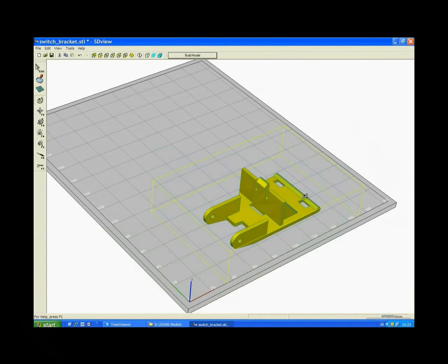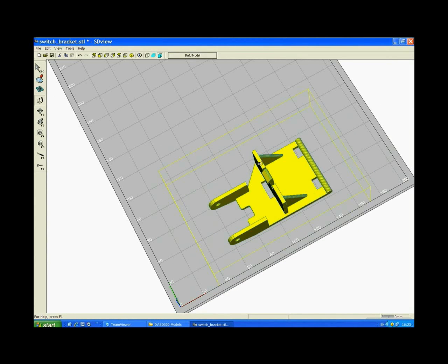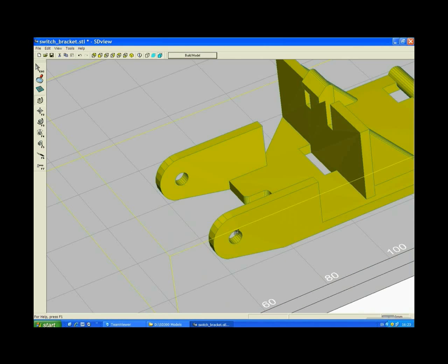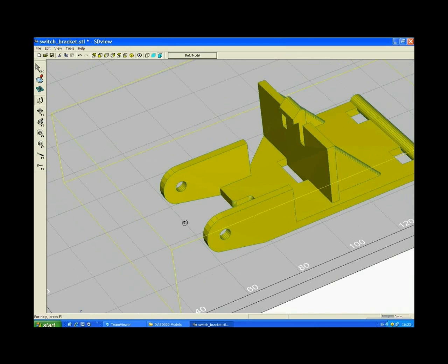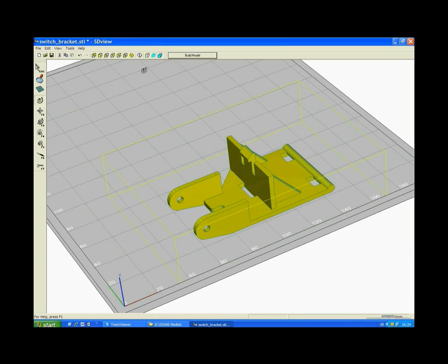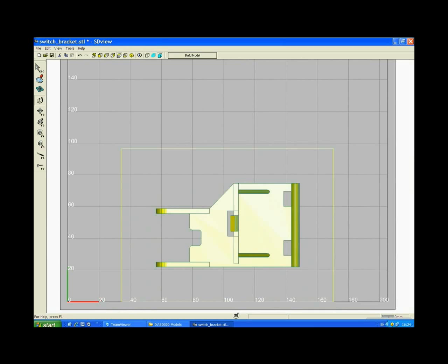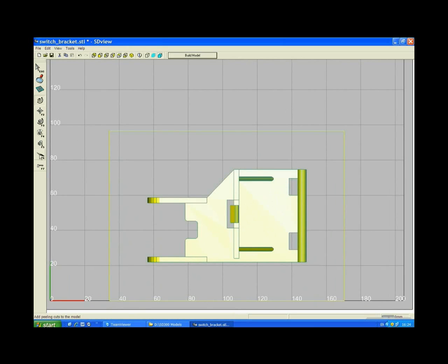When viewing the model geometry in this part, we will see that we have a wall going through the center of the part and two smaller walls coming out of the base of the part. Both smaller walls have openings in the X and Y axes. In order to remove support material around this part in the most effective way, we will place the following peeling cuts. Using the top view again, we will select the Peeling Cuts tool and run a peeling cut through the center of the main wall.